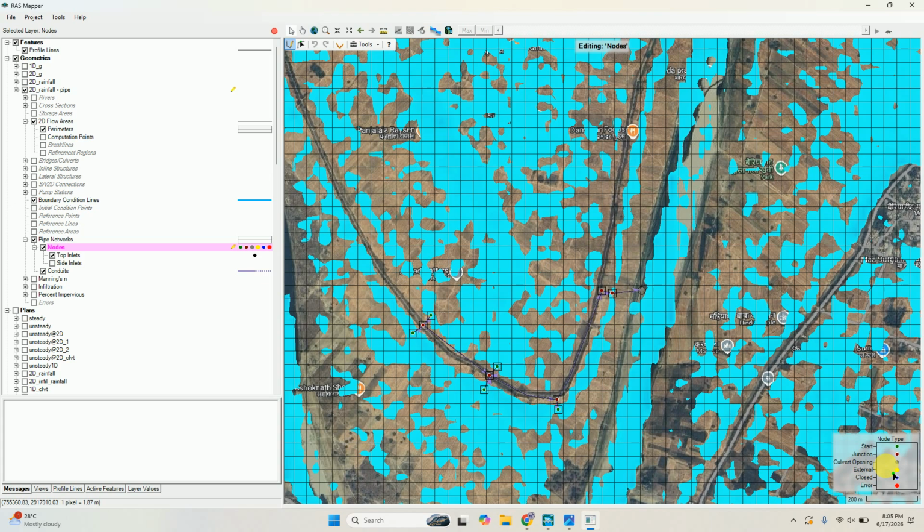Okay, the main thing I am going to explain is the start. At your node, you click where you want to create a manhole here, and after that you have to join all the manholes by the conduits, by the pipes, and after that you have to extract that pipe and dump that water somewhere. You have to dump that.